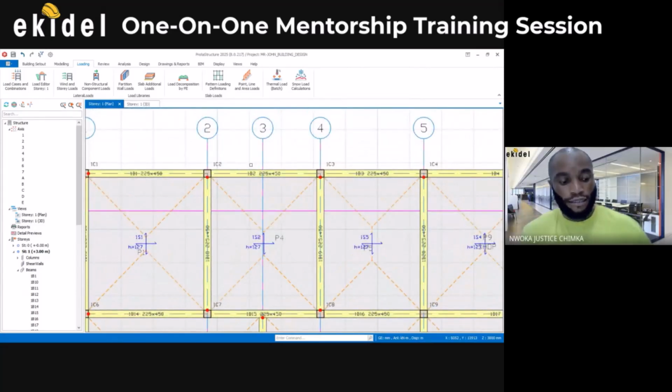Yeah, exactly. So for example, if the building will be having heavy loads, external loads, lateral loads and all that, you might choose not to apply hinge. It will be left as fixed, because you want those joints to be stiff.